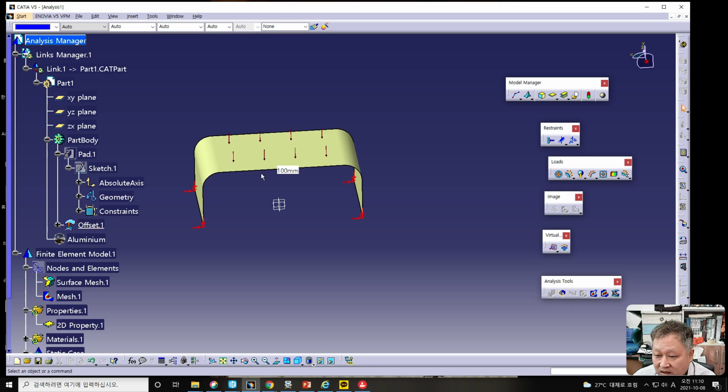If we give the boundary load in this direction, however, and the restraint does not exist, then the model would fall down, and infinite calculation would be conducted like this. Therefore, the error can occur. We should keep in mind that we should give the restraint condition. Giving the restraint condition is very important for CAE analysis.